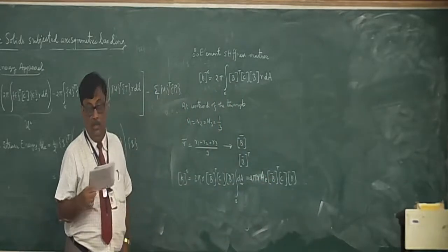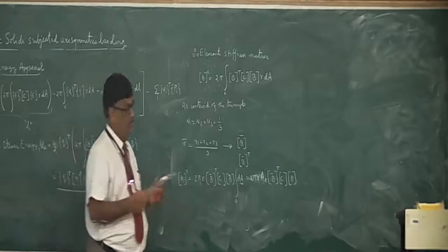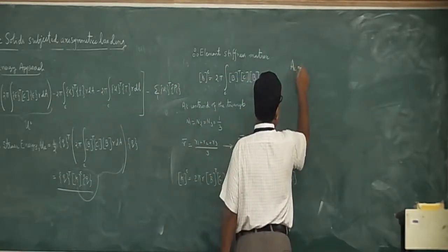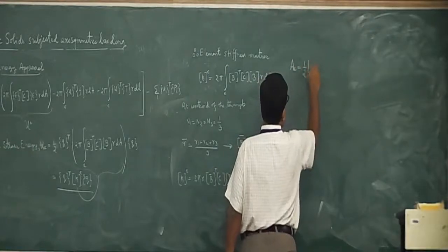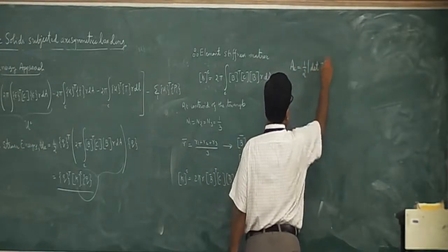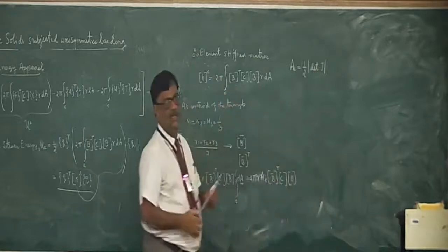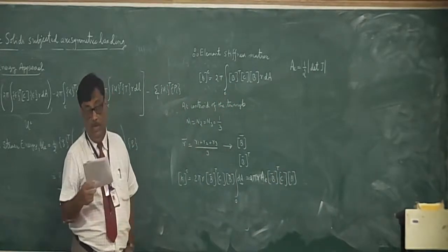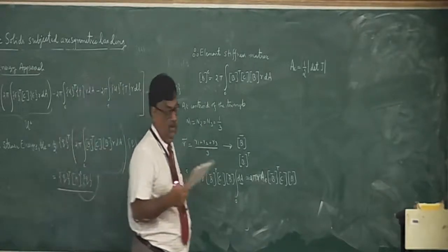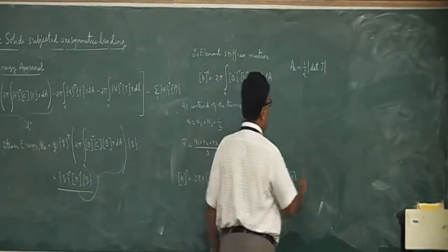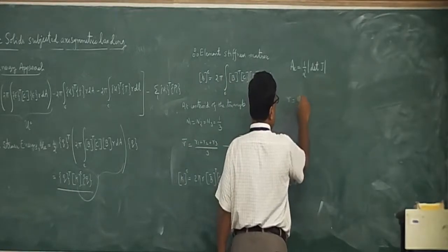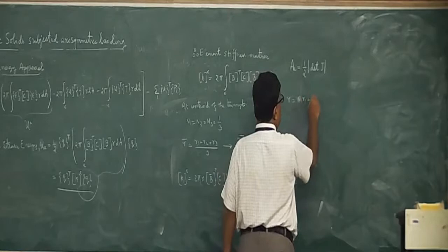So this is giving you the element stiffness matrix, and you already know the area of the element, which can be directly obtained by half of the determinant of J. You have already established this relation. From this you can directly find out the area of the element. Otherwise, if you want it at any other point, then R has to be found out by this relation.